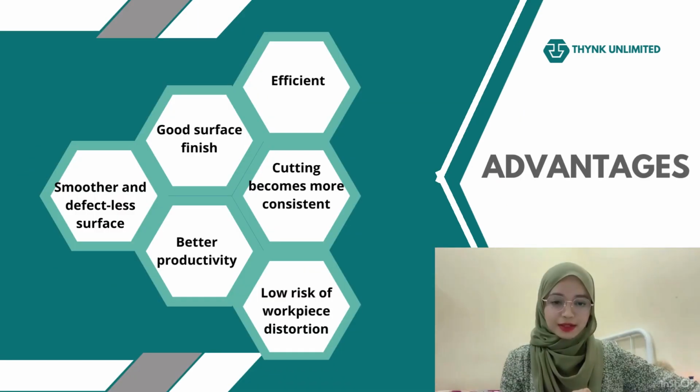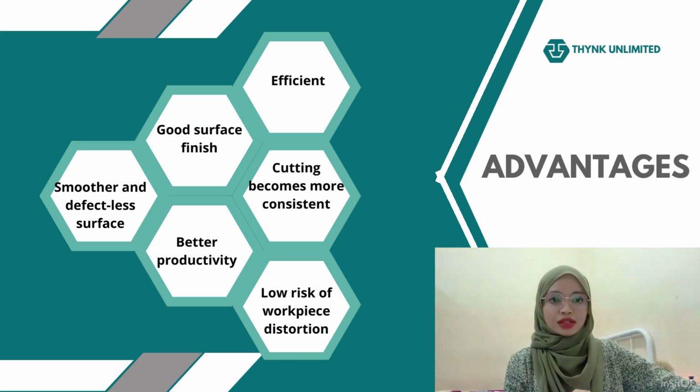Next is advantages. There are some advantages of the high-speed machining process of CNC, which are: the first one is a good surface finish. With high-speed machining, cutting temperatures are actually reduced. Surface finish is also improved, and the machine spindle and cutter acquire less wear and tear over time.